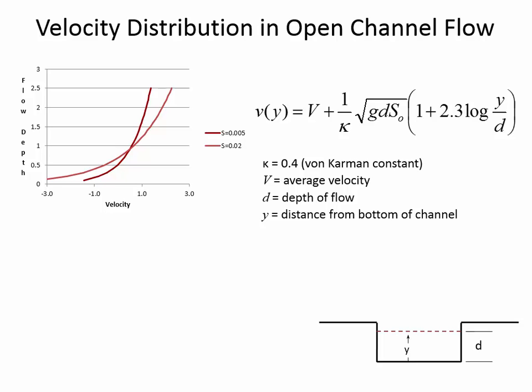One of the things that is in the textbook is the idea of velocity distribution. There's an empirical equation that estimates what that profile looks like. Let's take a look at this figure and discuss it. What it's showing is that if you graph this equation, the von Karman equation, it estimates that the flow decreases as you get further away from the surface.